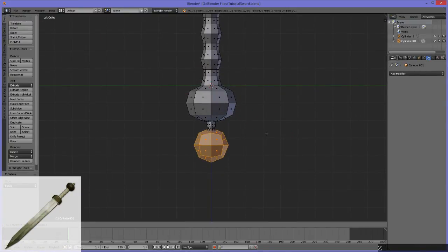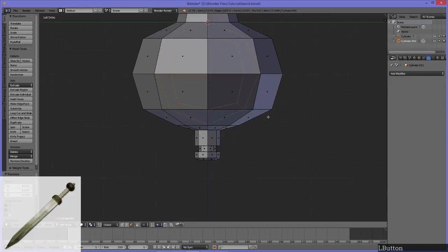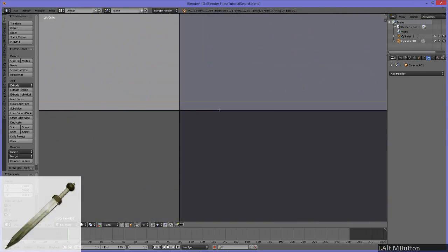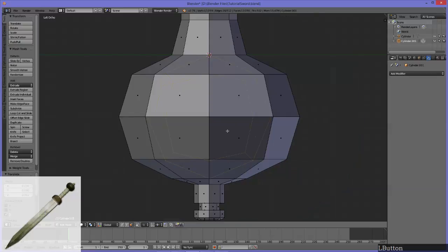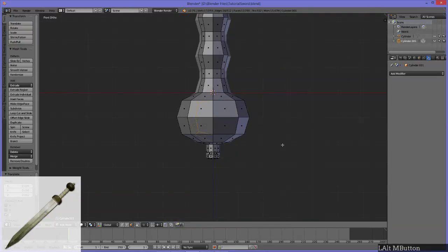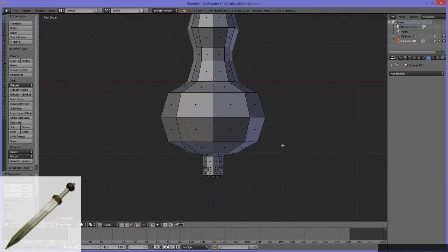We're going to bring it up to where we want it. Actually, I'll turn Q back on so we can see through it. Now we should be able to see it as it passes in. There we go. We can actually line that up exactly. We'll just zoom in super close and get it right on the dot. Ah, there we go. And then we can just hit GX to move it out.